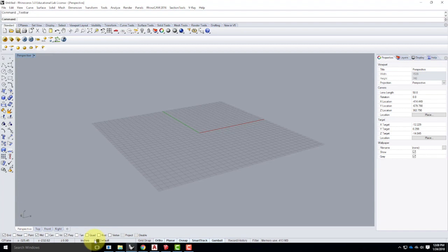If you set your units to feet, when we go to do renderings, you're going to get really funny looking materials because the units that are in the materials are again based on inches. So we're assuming everything's in inches, and you'll have to make adjustments if you choose to model in some other set of units. So I'm going to confirm right now that my drawing file is in inches.